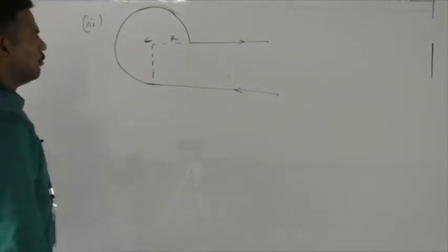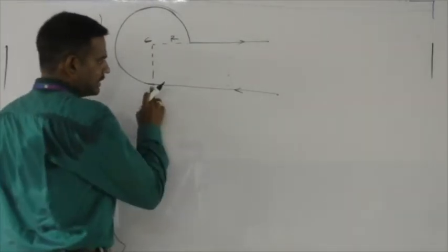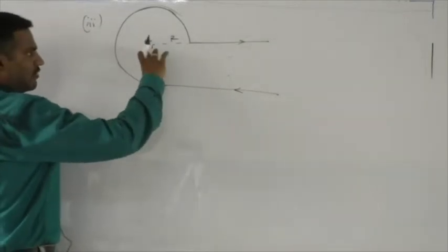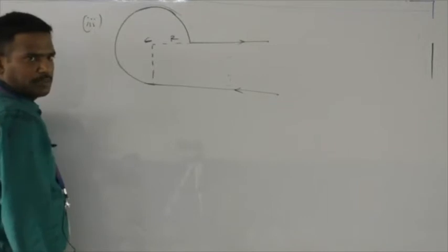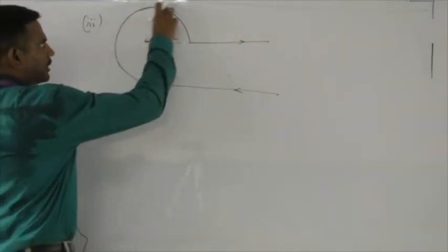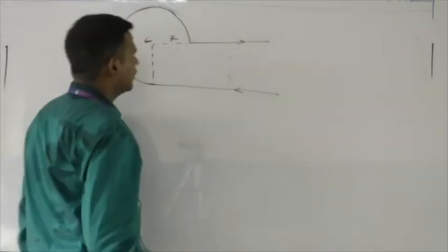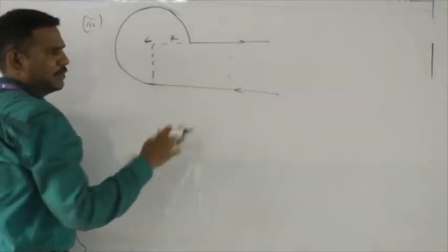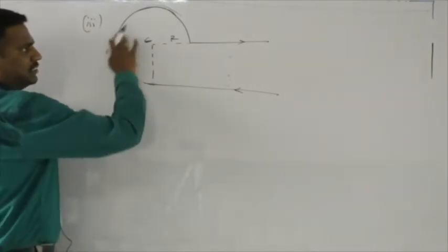First of all, how many conductors are there? Here totally 3 parts are there. One is infinitely long, such that the point C is lying at one of the ends. Therefore, it can be considered as a semi-infinitely long conductor. The second one is an arc-shaped conductor. The third one is infinitely long, but the point C is lying on the extended line. Therefore, due to this, there will be no magnetic field intensity. And so, let me go on with the calculation of these two.